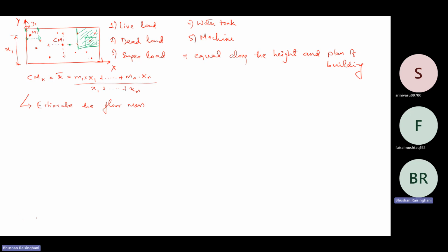But in small portions also, locally or globally, if the opening is very high, that portion cannot be termed as a rigid diaphragm. It will not transfer the forces. So we should not define it as a rigid diaphragm in that particular case. So this way,